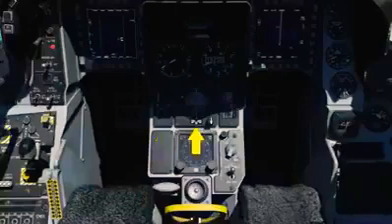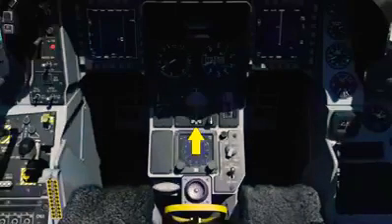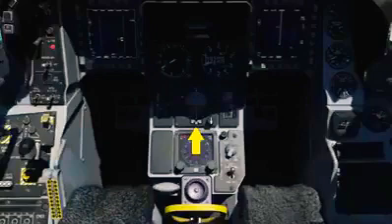The Attitude Director Indicator, ADI, displays the aircraft's pitch and roll attitude as supplied by the Inertial Navigation System, or INS. The indicator also includes a turn rate needle, where the needle's width equates to 1 to 1.2 degrees per second, and a ball and slip indicator. The pitch trim knob can be used to adjust the sphere in relation to the aircraft symbol. When the instrument landing system is enabled, the ADI can also display the localizer and glide slope bars along with associated warning flags. We'll talk about this later in an ILS video.